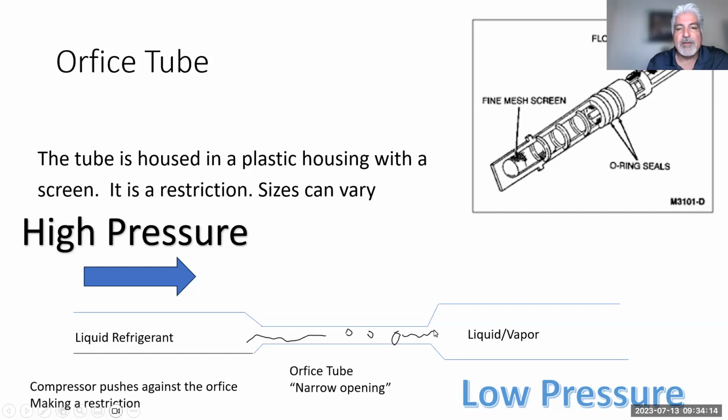So therefore, some of that refrigerant will start to boil. So eventually when it goes past this tube and goes into the evaporator, it's going to start to actually boil, but it's absorbing heat, like we said already. So therefore, that is normal of an orifice tube system. But the farther the liquid travels through that orifice tube, the more it stays in the liquid state, the more apt it is to carry more heat out of it.